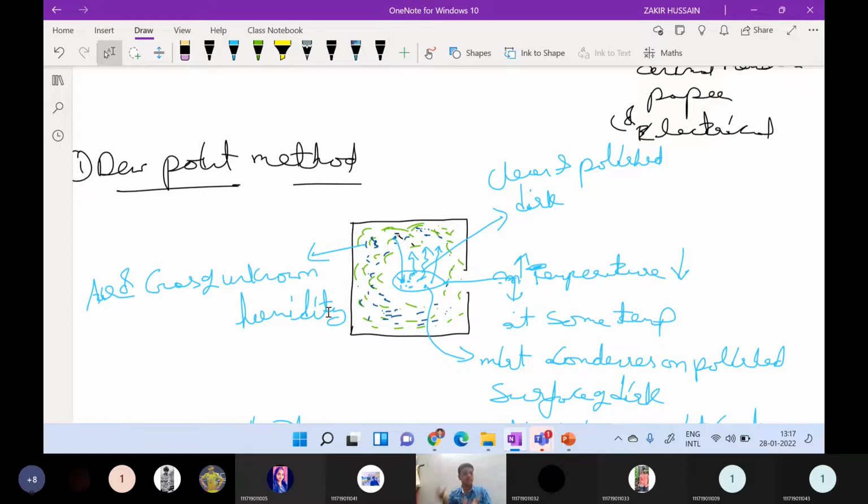To check whether the dew point temperature estimated from the conversion of vapor to liquid is correct, the temperature of the same disc is now increased. The point at which all the mist disappears is also called the dew point. The point of mist formation and the point of mist disappearance are averaged, and over a number of readings an average temperature, called the dew point temperature, is reported.